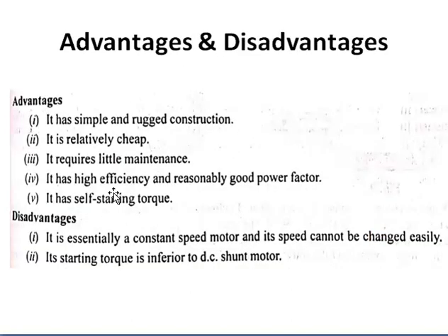Next, the advantages and disadvantages of an induction motor. The advantages are that the induction motor has a very simple and rugged construction. The construction is very simple, and it is mechanically very strong. It is relatively cheap, economical, and requires little maintenance. It has a high efficiency and reasonably good power factor, and it has a self-starting torque. So the induction motor can start on its own.